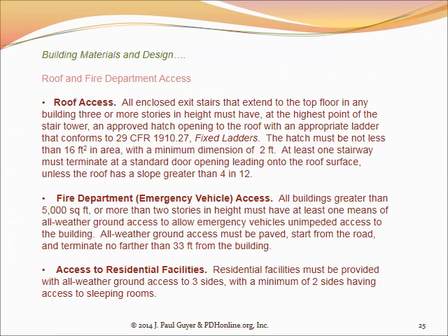And that's why you always see stairwells constructed with a very high level of fire-resistive construction, poured-in-place concrete or masonry walls. And that is the channel that the firefighters have available to them to move from outside the building up to the 5th floor where the fire is, and put the fire out with their hoses, or move up to the roof and keep the roof wet.